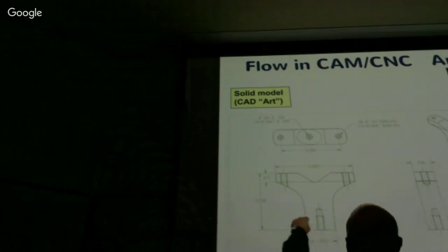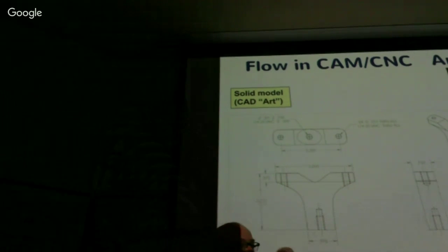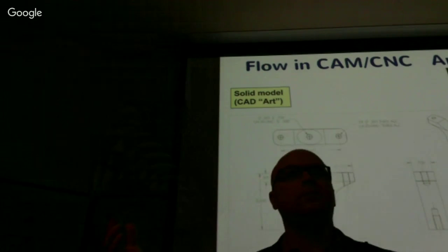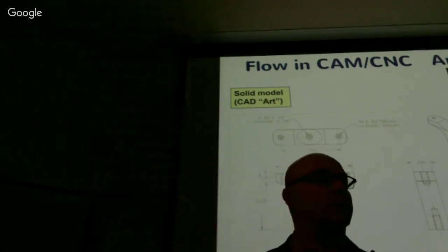So this right here says that it's 2.25 inches tall, right? Well, 2.26 inches tall works just fine for me too. 2.24 inches tall works just fine for me too. So I can have a band of lengths there. And the bigger that band of lengths that I give it, the cheaper it is to make. Does that make sense? As a general rule, the larger the tolerance I give on a dimension, the cheaper it is to make that dimension, because the manufacturing person has more options.